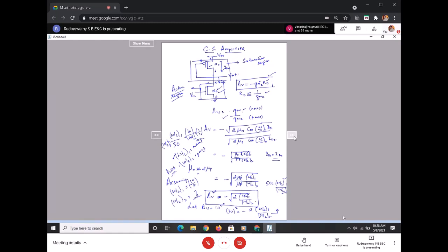After having this schematic, then we will be going for 3 analyses. First we have to go with the DC analysis, then we will go with the transient analysis, and then finally we go with the AC analysis. And why this DC analysis we were doing for this inverter circuit is very much visible over here. This is what the design of common source amplifier is all about.